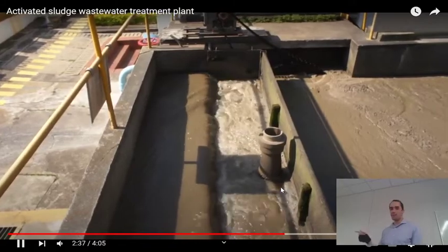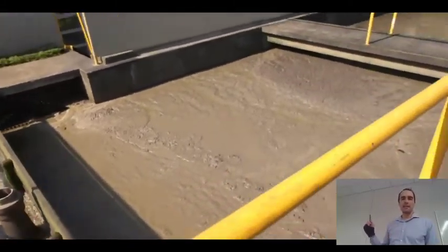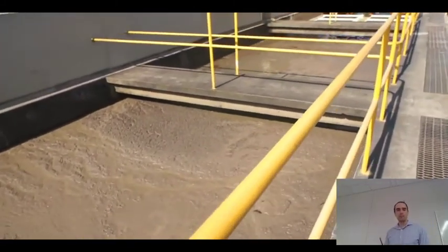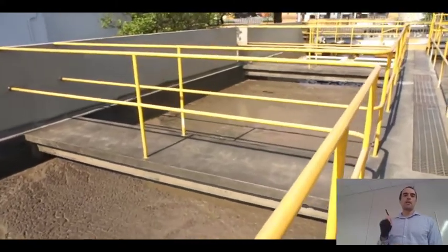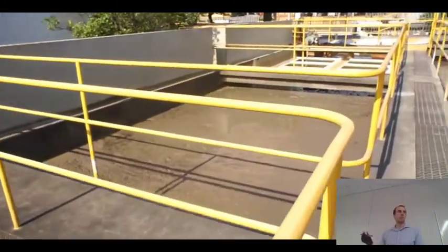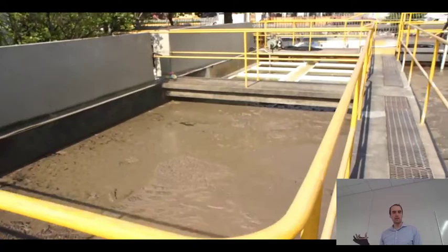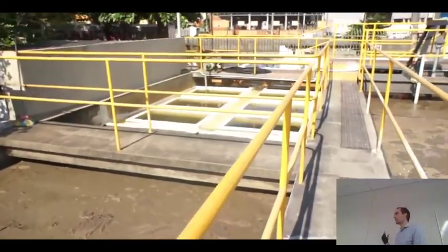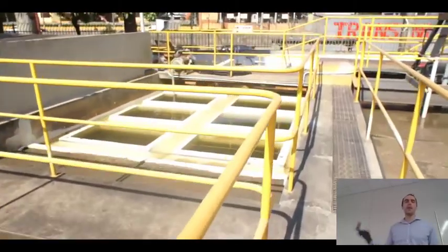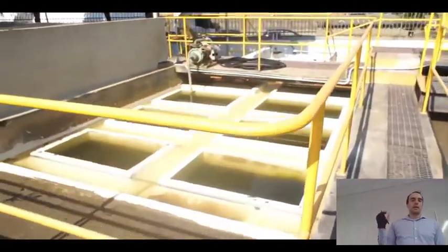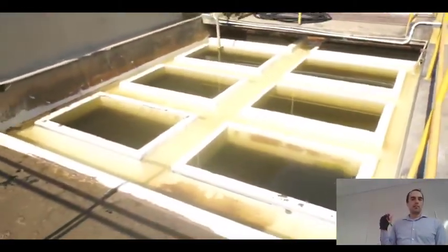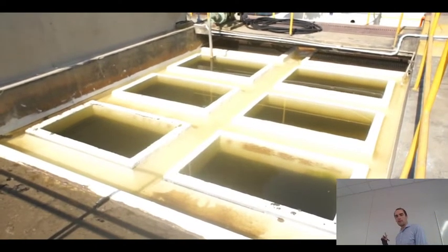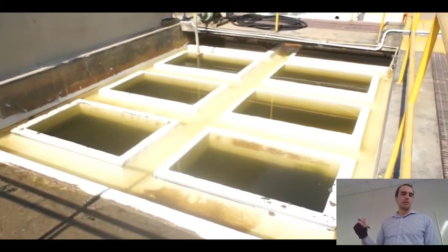All right. So then from there, I think we're taking that, and this right here is probably that secondary clarifier. You see a lot of foam scum accumulation along the top, so they're not going to take directly off the top. It's pretty typical after you've given it so many bubbles. It's going to have some of that. And then, not actually sure about this, but that might be a disinfectant contact chamber.